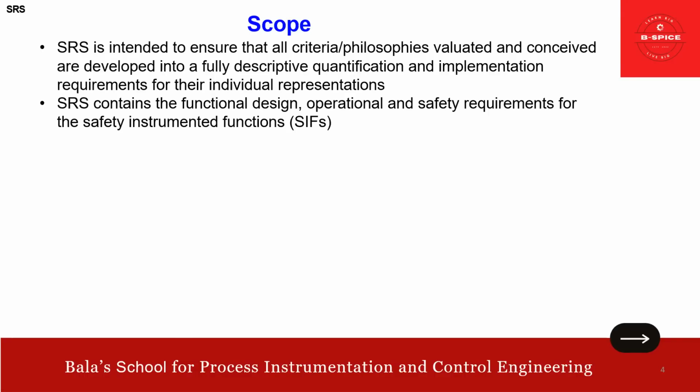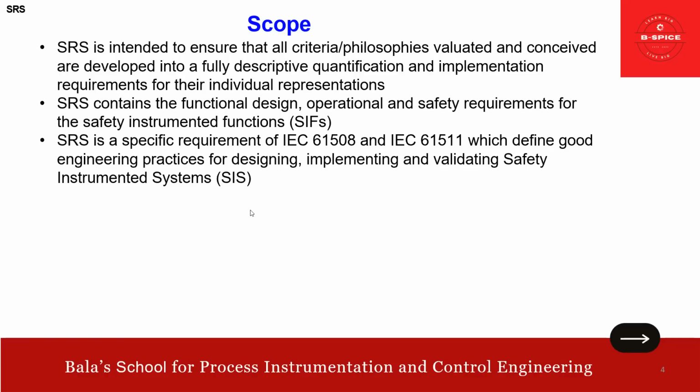SRS contains functional design, operational and safety requirements for each SIF. SRS is a specific requirement of IEC 61508 and IEC 61511, which define good engineering practices for designing, implementing, and validating safety instrumented systems.